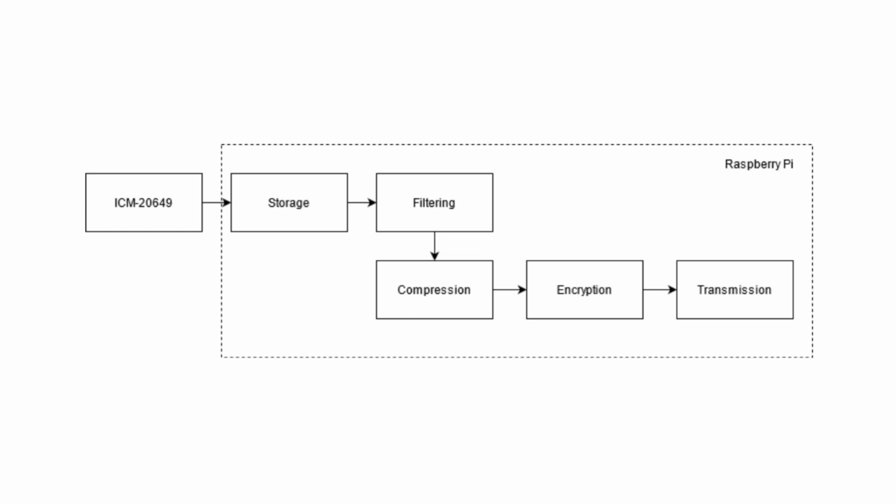The simulation was conducted by replacing the ICM-20649 IMU block with a data source that fetches samples from a CSV file of sample data. That way, the interface between the data source and the rest of the system remained consistent regardless of the actual source of data and required minimal changes to the code base when switching between simulation and hardware.